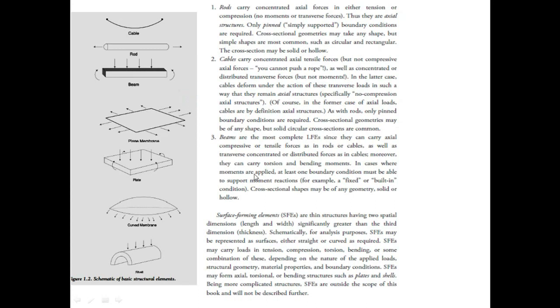Let's go ahead and see what this says. They can carry axial loads, compressive and tensile, as in rods or cables, as well as transverse concentrated and distributed forces. Moreover, they can carry torsional loads and bending moment loads. In cases where moments are applied, at least one boundary condition must be able to support the moment reactions, for example fixed or built-in conditions. Cross-section shapes may be of any geometry, solid or hollow.